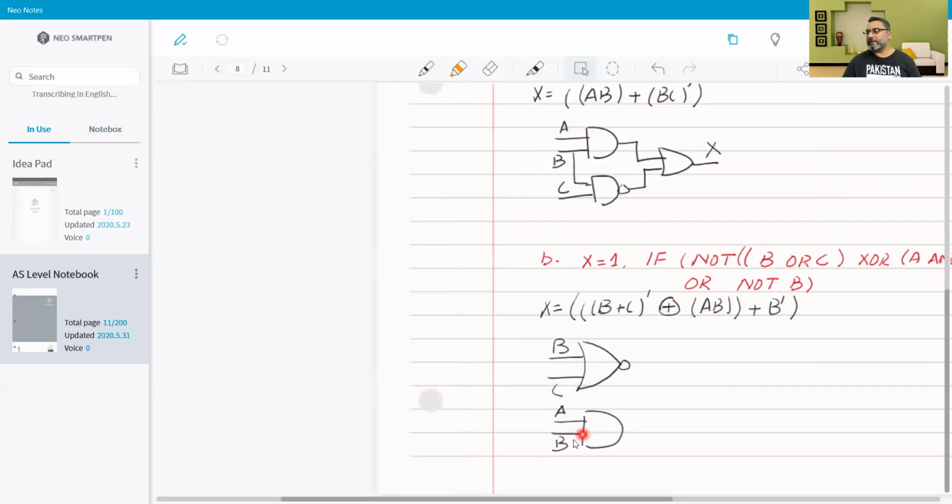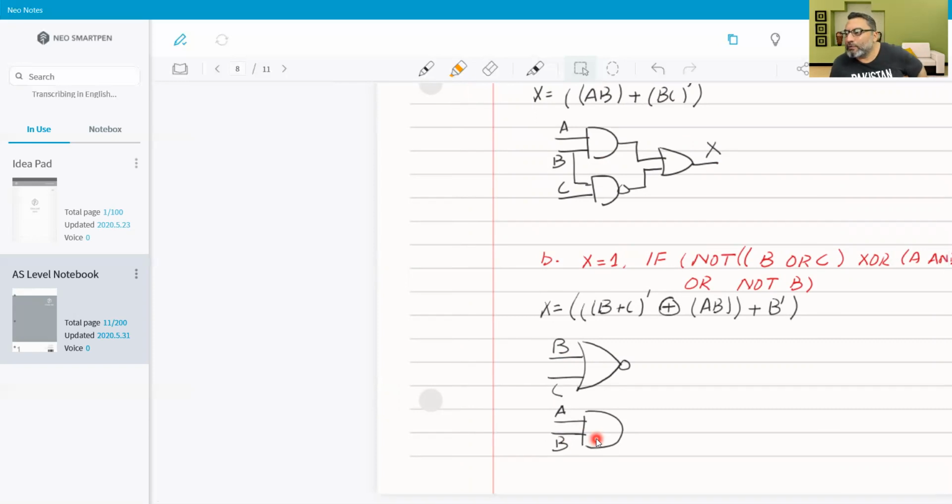Another thing that you need to remember: it is not always necessary to bring in lines from one variable to another gate for another input. It is absolutely okay if you represent the same variable many times. No matter how many times you show that variable separately, instead of bringing in lines from the first input, it is regarded as one.